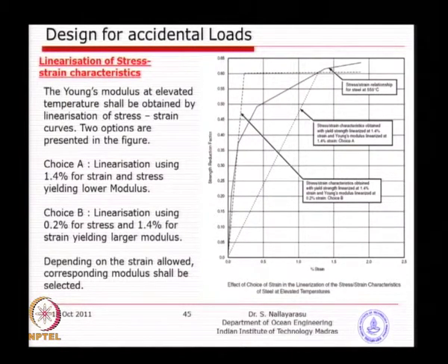because you are taking higher stiffness in your system analysis compared to the second one, and most of the time both of them are not correct, because if you have a value of your stresses at this part, maybe that point is correct, but what about in between? In between you have continuously changing values of the ratio of stress and strain, and if you take only one value as a representative, it is because you are doing a linear static analysis, a simplified structural analysis.